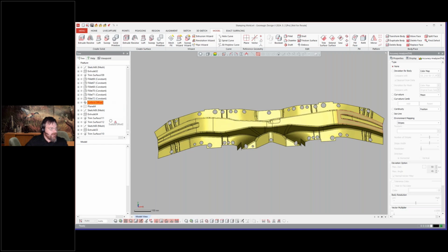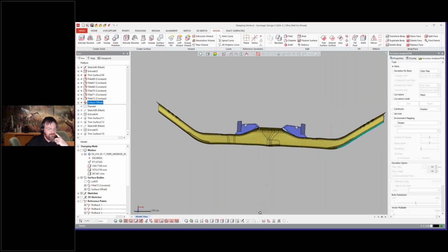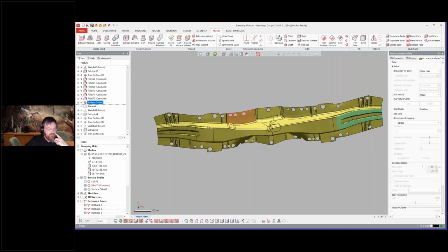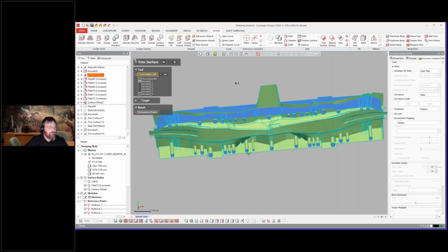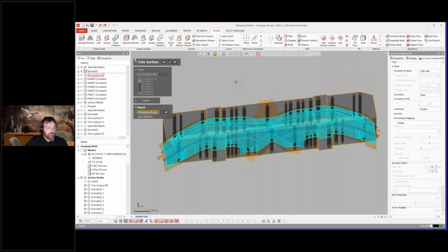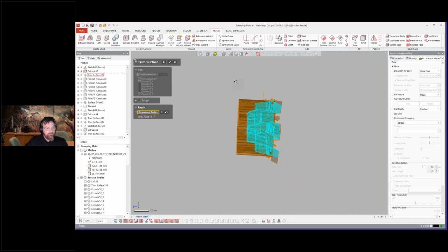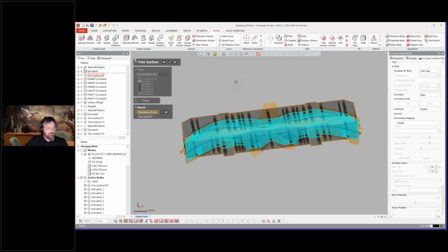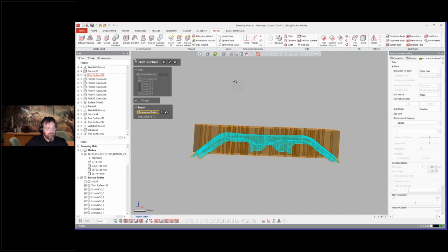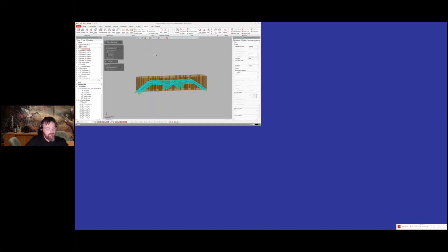Now you see that we've added a ton of the hole cuts, and there's a bunch of them you can combine together if they're on a similar plane, right? So if they're on a certain direction, a lot of these you can cut all together with, I believe it was this one right here. Let's see here. Yeah, so look at all these holes that were cut at once. So we cut the outer boundary, did an outer boundary surface extrude and interior holes and modeled all those at once.